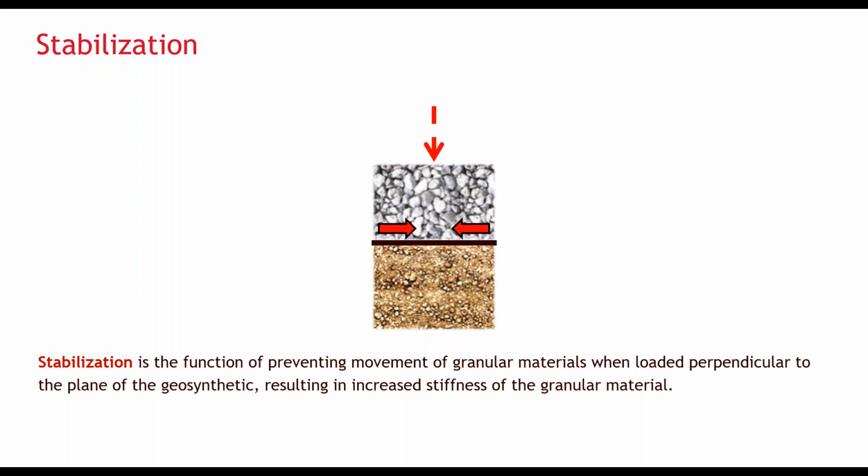The key distinction is the difference in loading conditions. Stabilization enhances the performance of granular layers when loads are applied intermittently and perpendicular to the plane of the geosynthetic. The most common application of the stabilization function is to enhance the performance of aggregate layers in roads.